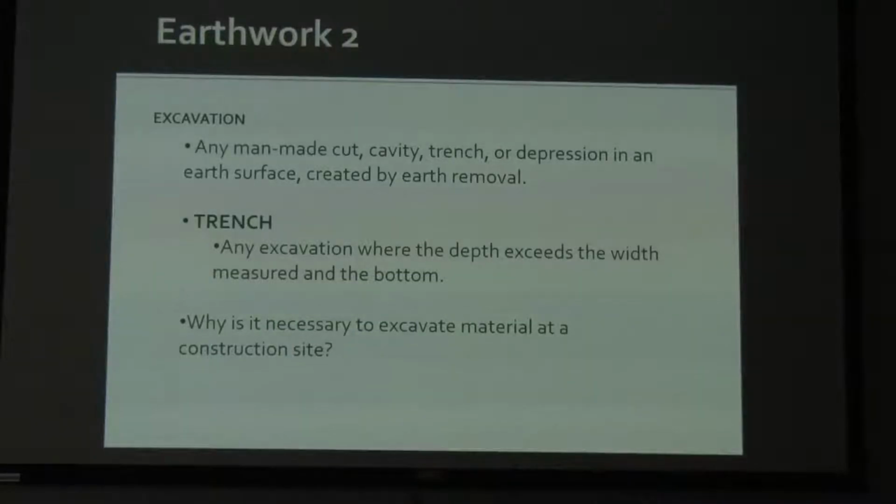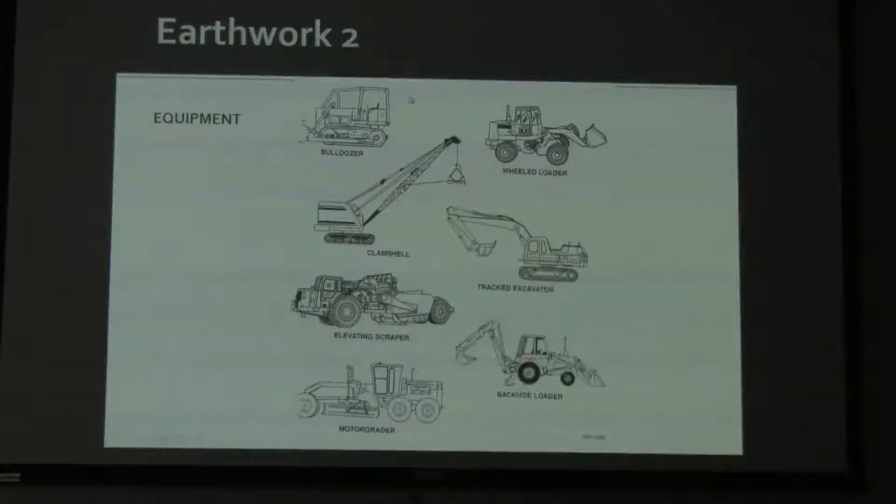For instance, we'll trench maybe to put in some type of drainage structure, or we might excavate to build a foundation for a vertical structure, or for a bridge, or sometimes we'll want to excavate material because it's poor soil and we want to replace it with a more desirable type of material, or a select material, as the Department of Transportation would call it.